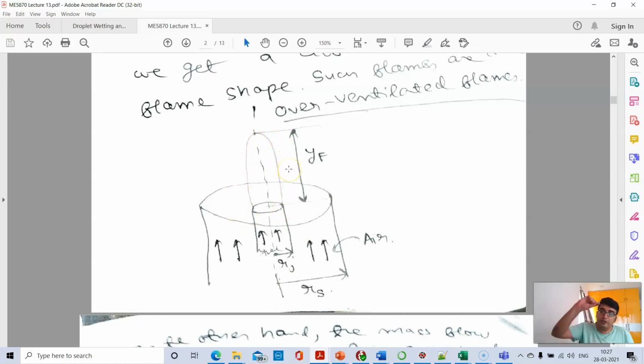In the boundary between the two flows, diffusion-based mixing happens, and that's where the flame is generated. These are called co-flow burner setups, and these are quite popular ways to create diffusion flames within combustion chambers. Usually they are turbulent diffusion flames, but the basic structure is similar. You have an outer air flow and an inner fuel flow, and they are mixing at the edges, and these are called co-flow burners, as I discussed.